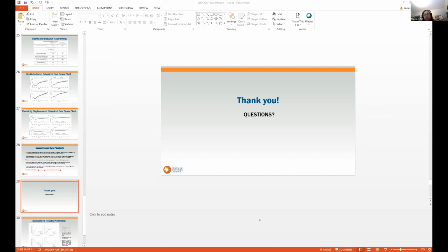The carbon dioxide's liquid in the formation. It's pretty wet. It's got some other impurities. And during what they call productivity testing, but it's really just a sort of well cleanup, they vent carbon dioxide to the atmosphere for days at a time, sometimes millions of cubic feet of gas. So I'm just wondering if those things are in that model.